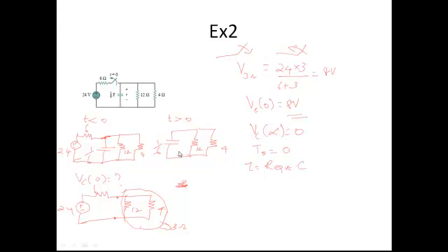If it is only one resistance, you can take it directly, but if the circuit involves more than one resistance, you have to get the equivalent value. You can see directly that 12 ohms and 4 ohms are in parallel, therefore R equivalent equals 3. So tau is equal to 3 into 1 by 6, which is 1 by 2 seconds, or 0.5 seconds.